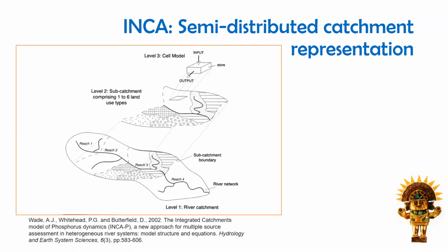If one has a GIS layer of the catchment with catchment boundaries, with river network, and with some sort of estimates of land cover, a catchment can be divided into subcatchments, and typically the division of subcatchments is made either where there are big changes in the way the river is flowing, or perhaps where there is a monitoring location, so it's possible to calibrate, or where there are sort of divisions of management interest.